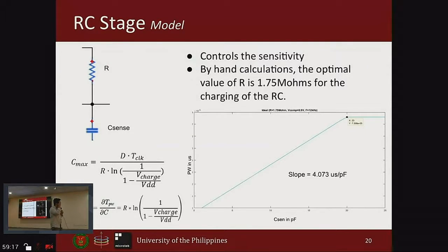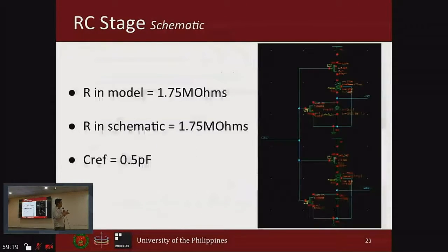So the main difference here is that we still have the resistance, but now in terms of the implementation, we also have a transistor that is parallel to the capacitance. Because right after you've charged the capacitance at the target threshold level and the duty cycle, when the clock begins to transition from high to low, the objective is to pull down the charges from the capacitance to be able to reset the circuit.